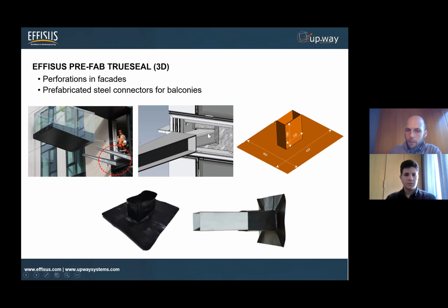We can also provide this with an open joint, because when you have things like this, you are not able to put the sleeve from the top of this arm, as you're facing a larger section. So you apply it all around the smaller section, and having this open joint will allow you to put it all around and then close it easily on site.